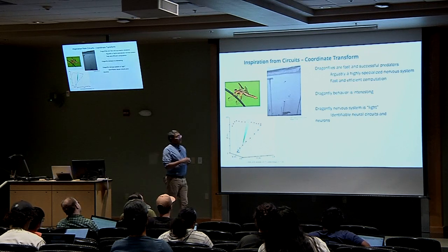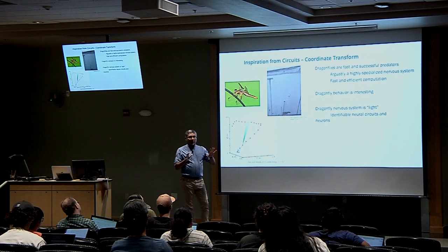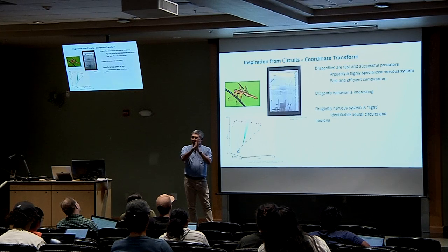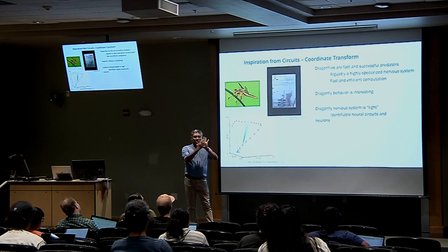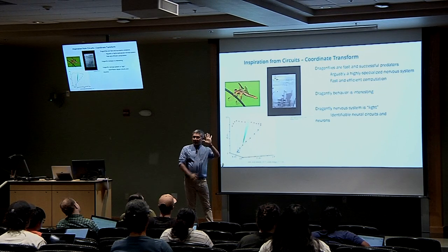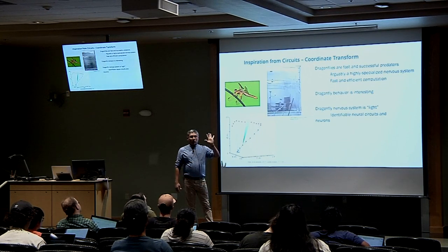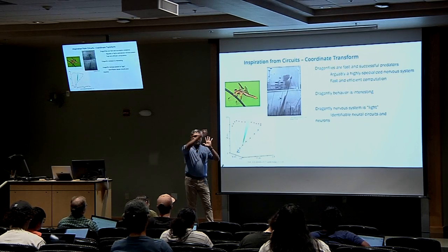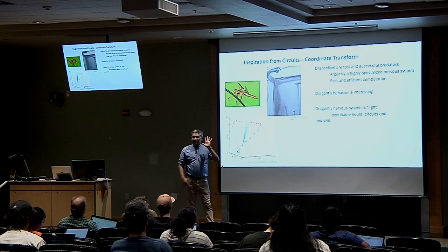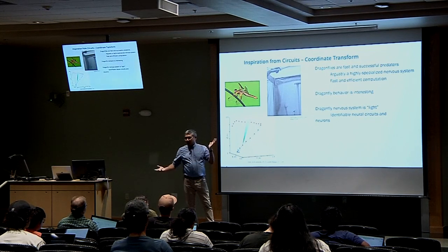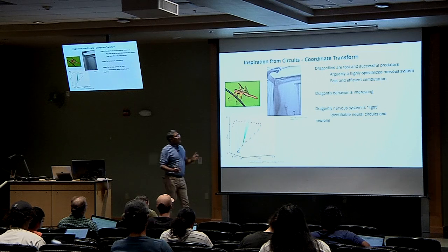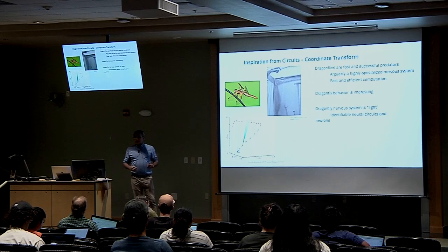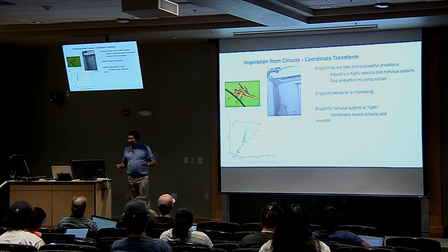The calculation of this guidance law is simply coordinate transformation. Because in the dragonfly eye frame, you identify your prey, and you want to know, if on this image plane I see the prey here, where is the prey in the real 3-dimensional space? There's a bunch of matrix multiplication that needs to be solved. If you've done any graphics or robotics course, you can calculate this out on a sheet of paper or two.